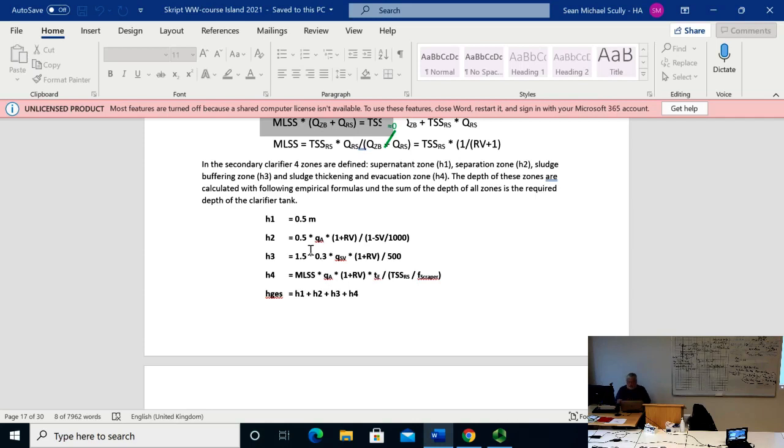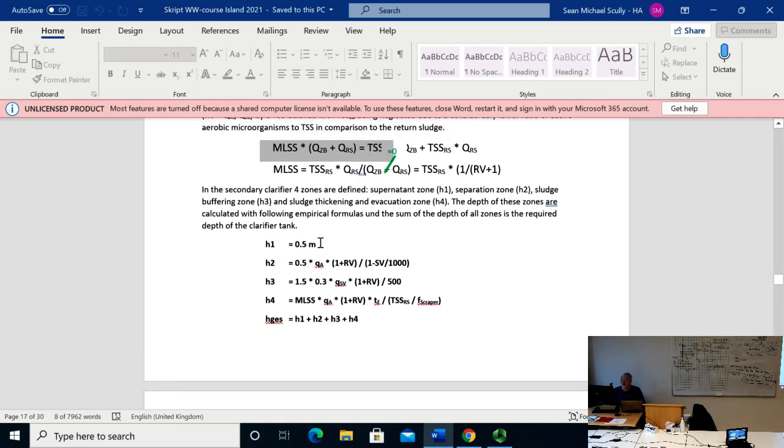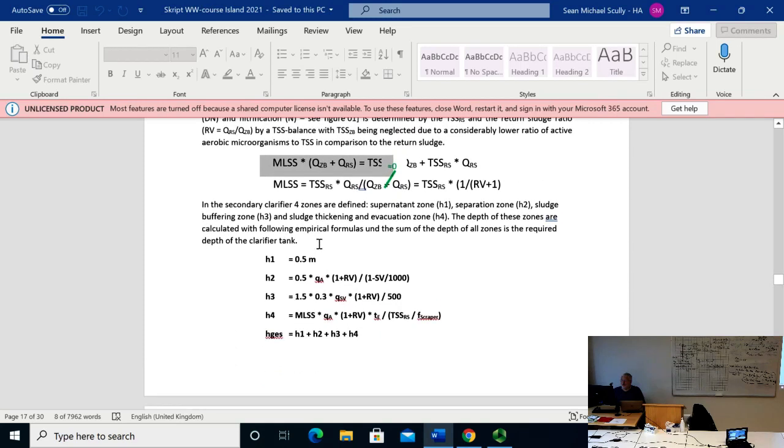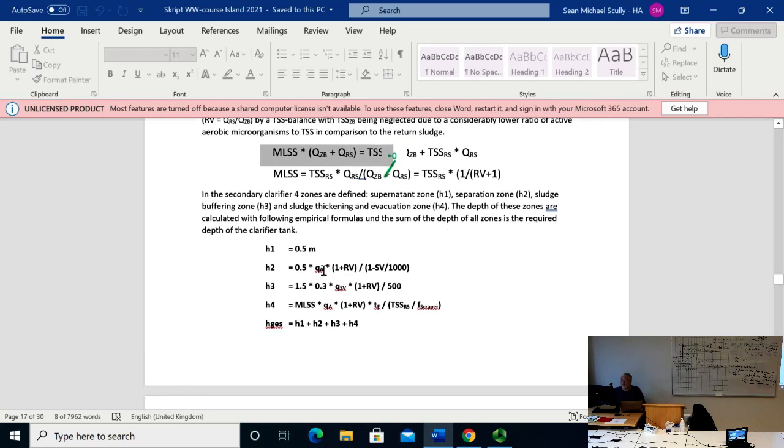Okay, that's a very low rate, however. Well, you know, it just is putting in the stuff in the formula here. The QA is actually, no, this would be just, because you have to put this times 1.75, because this QA just assumes for, it doesn't assume for the return sludge.